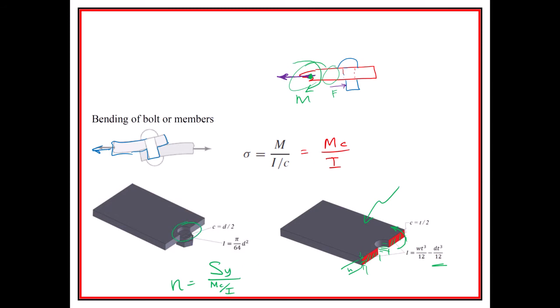I'd also point out sometimes they also try to look at the bolt right there, and they could say that the same moment is being placed onto the bolt, and it too is being bent. But I really kind of think of that as needing to have sort of a gap in there, because the bolt is going to remain relatively straight. Saying there's a bending moment on it, I find it a little bit difficult to buy, but I guess if you were to put the force right here and hold this steady right here, there would be a bending moment on that. So I guess the bolt could bend, but it just seems to me that you actually need some kind of physical gap to be placed on there.